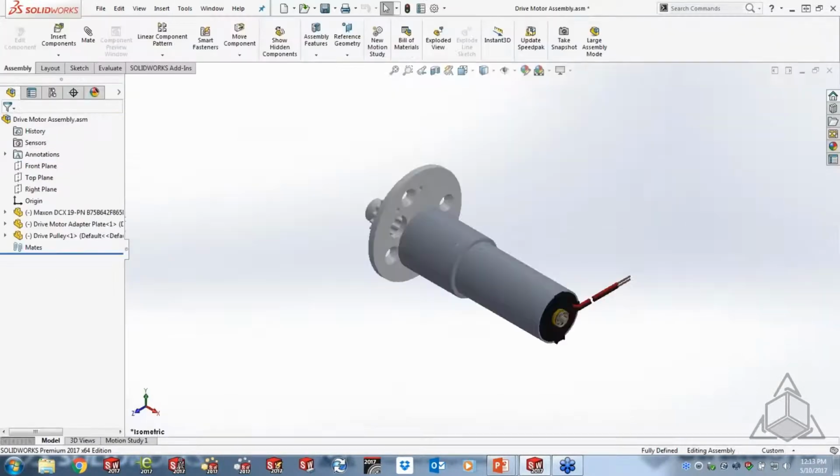Some formats are treated differently inside of SOLIDWORKS than others. You'll notice that when I open the Solid Edge, it does create an assembly with all the files. And to go back onto that Inventor file for a moment, the reason why Inventor does an import is because one of the SOLIDWORKS requirements is I have to have Inventor View or Inventor on the system to do a translation of the data. With Solid Edge, it does a translation, it brings in the parts, but let's think about this for a moment.